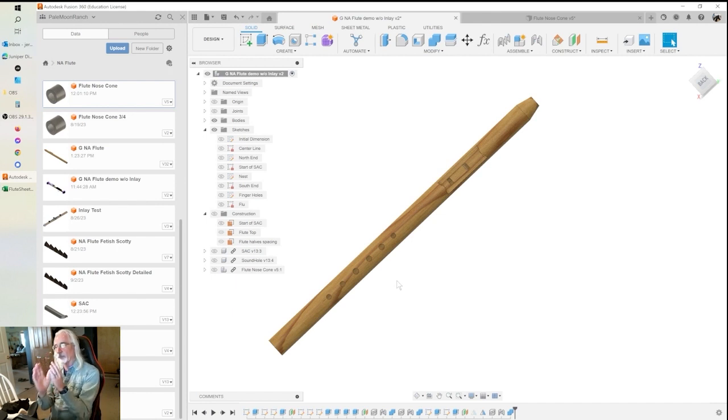And cut that down the middle. That way, it folds apart. You cut out the inside. When you fold it back, it still looks like it was cut out of the same piece of wood. If that makes sense. And to be clear on that, the stock needs to be 1 1/4 inches tall and 1 1/4 inches wide plus your blade width.